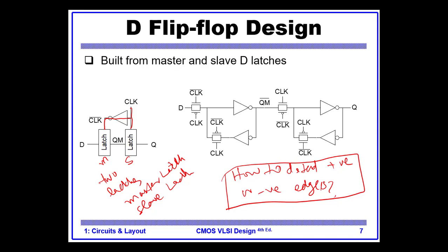Interestingly, the flip-flop is not level sensitive, it is edge sensitive. It stores the bit or changes the state at the positive or negative edges, not at the level. So you see, this is level 0, this is level 1, and this is the edge. A flip-flop changes the state or stores a bit on the edge.